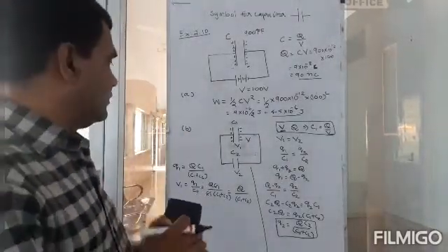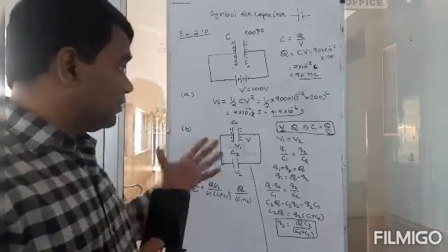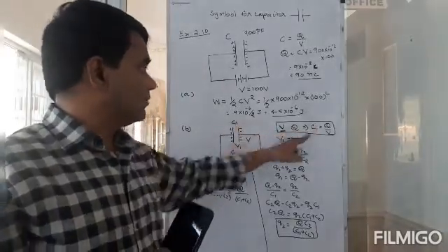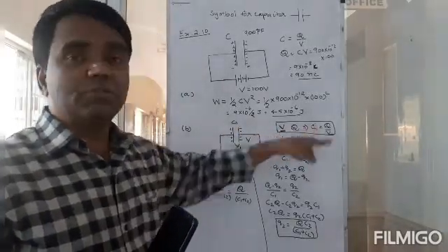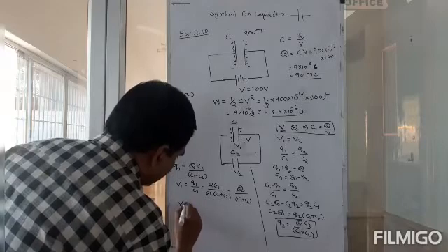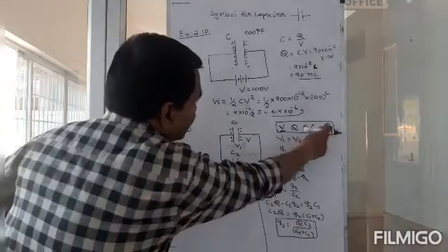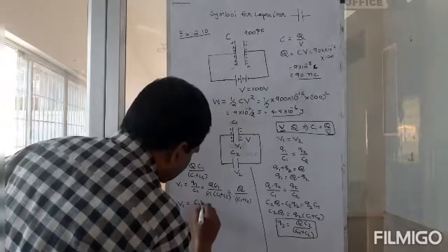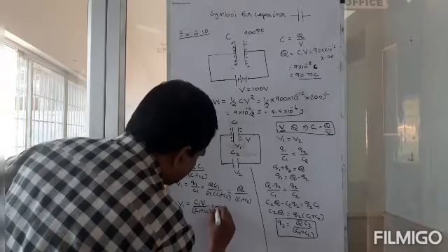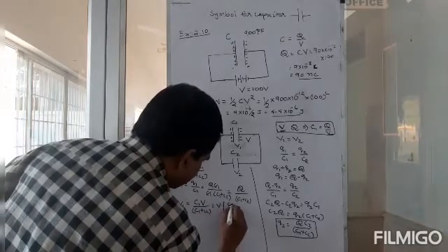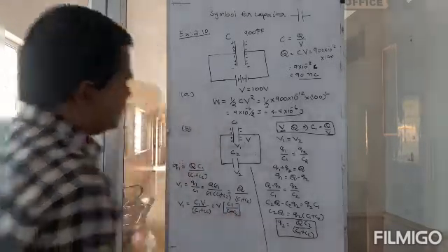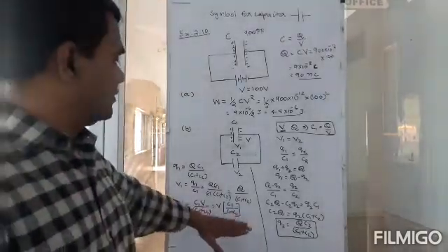Okay? But what is Q? What is capital Q? The beginning. That was equal to C1 into V, right? So I can do it here. V1 is equal, instead of Q, I want to say C1 into V. That was the original thing, right? By (C1 plus C2). So that is going to be equal to V into C1 by (C1 plus C2). Okay? So this would be the voltage shift.